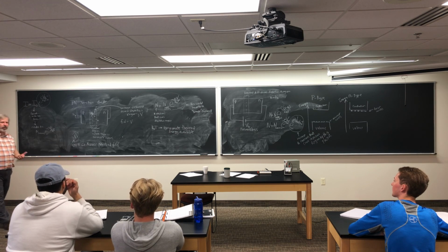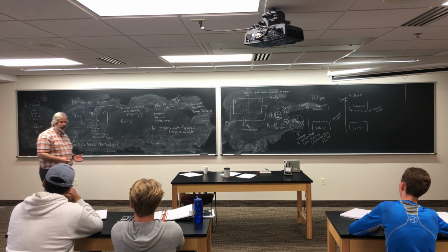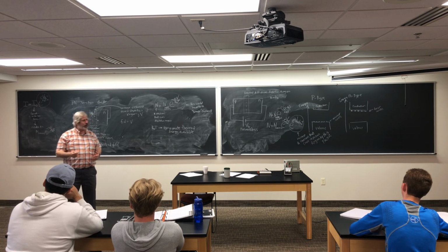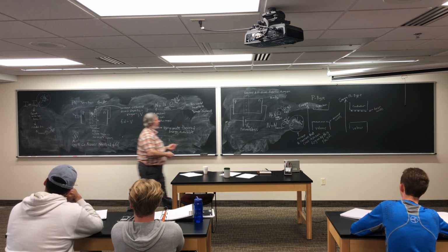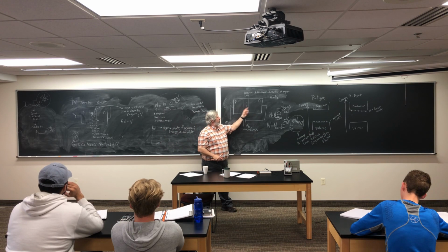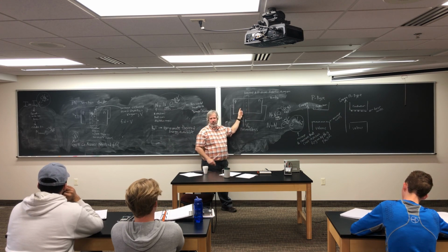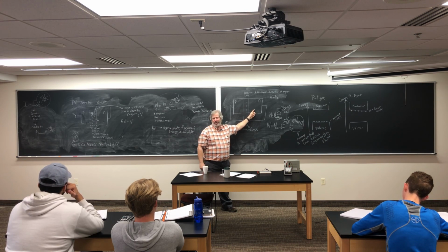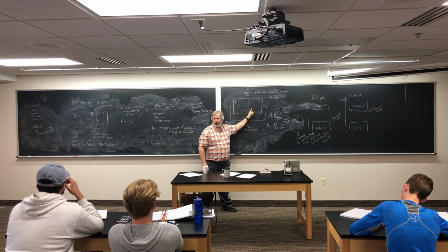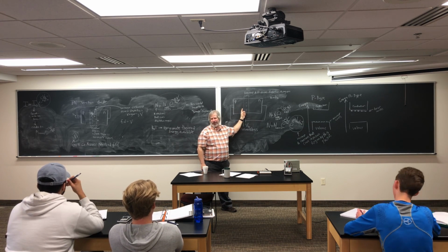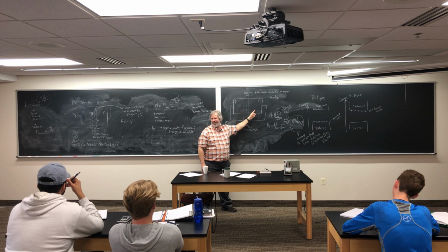Now, that's not all there is to the story, because even though you put this forward bias on it, and you're making it easier for electrons to go over here, every once in a while an electron that was over here will go back, right? So before, when I said you had that I naught, you had a probability when the electron could go over, you also had the probability the electron could go back too.